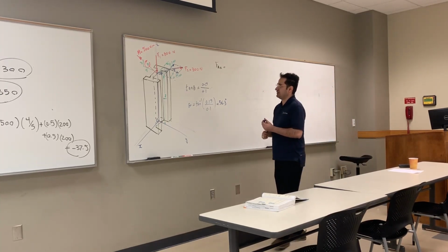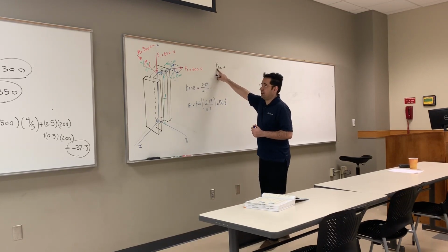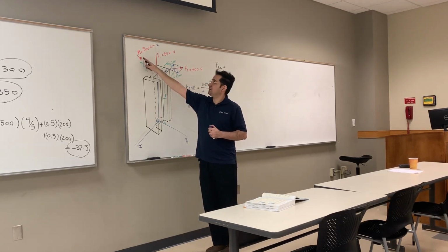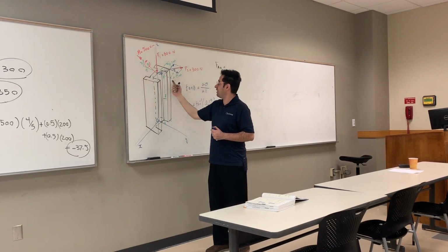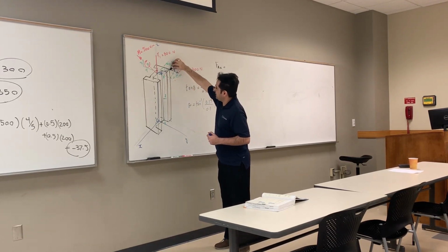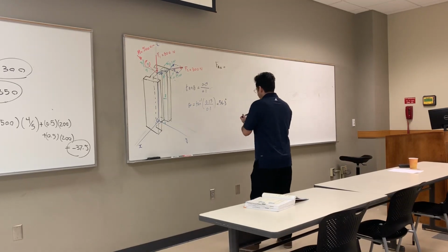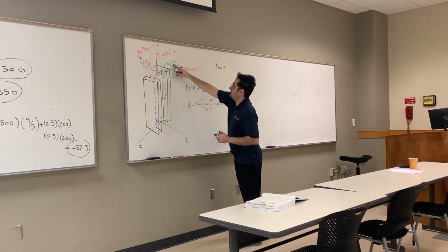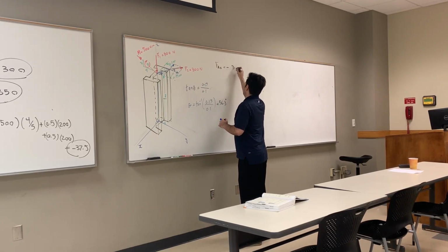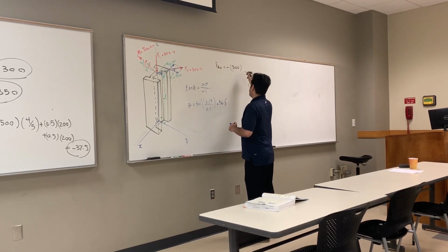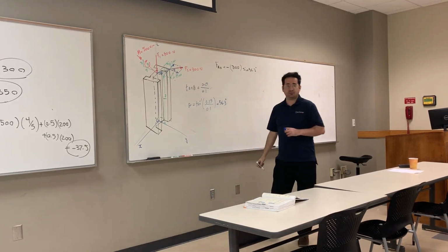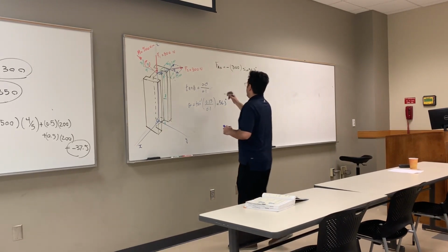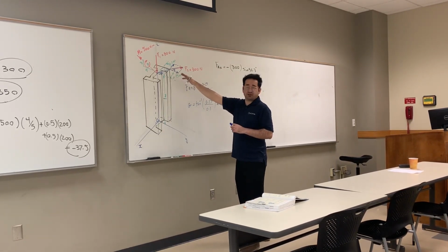Now let's go ahead and write the resultant force in the x component. As I said before, this has nothing to do with the force, it's just a moment, so you don't add it to the force equation. This one is in z, nothing with the x direction. This one is in a y, so this one is in x. Positive or negative? Negative. Negative 300 times sine 56.3. Right? Now, I'm done with the x direction.